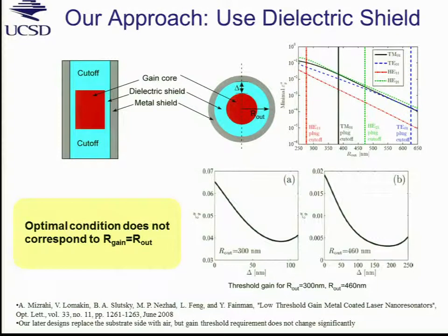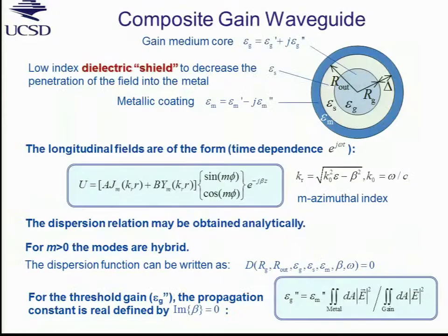The second thing that we exploit here is the creation of a photonic mode. We need to have some kind of a resonator. So we don't want the radiation to propagate away from the gain media. To achieve that, we basically use a simple idea of a waveguide in cutoff. So this is classical impedance mismatch, and all the field is reflected. So all energy is stored in the gain media region. So these are the 2 basic ideas. I'll walk through with you what we have done.